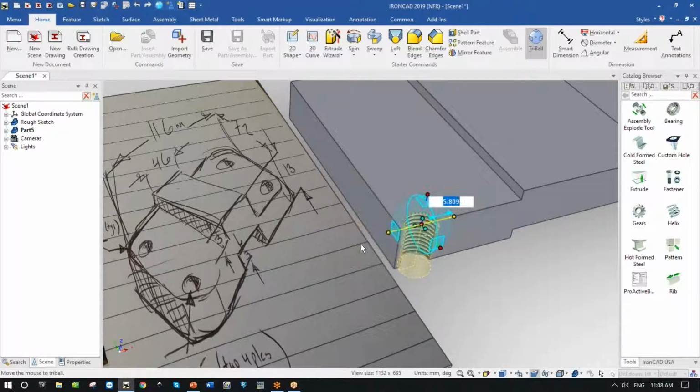Take this, move this over 10 millimeters that way, and then drag this handle and simply push it in 10 millimeters this way. So that was a simple way to guarantee that I'm 10 millimeters from this face and 10 millimeters from that face. But there are even easier ways to do that using the tri-ball. And, you know, let's undo again, bring it right back to the beginning.